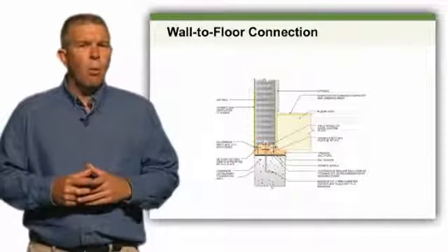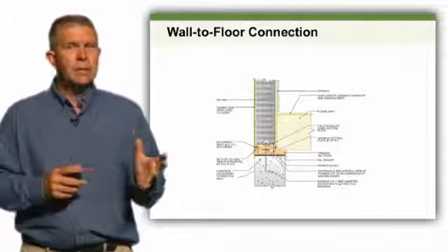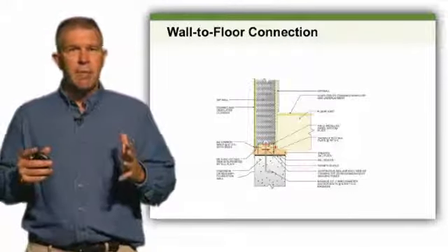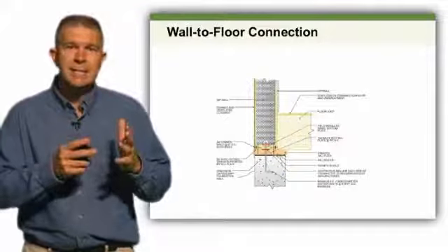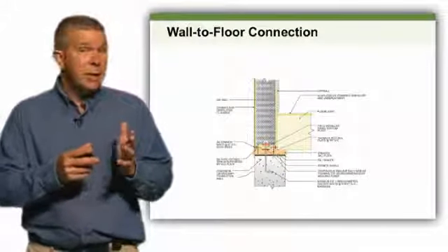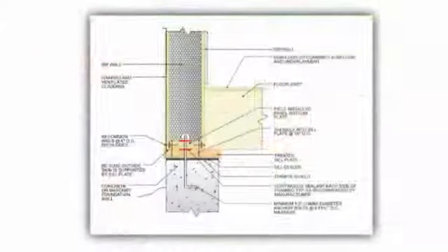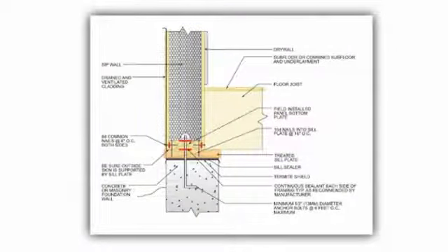If we're talking about wall SIPs, we have a couple of standard details that we're showing you here that incorporate the wall SIP as it attaches to the floor. Now, I say floor, it might be directly to the foundation. What we have here is a wall panel that goes down and caps the end of the floor system, and the foundation actually shares the support of both the wall as well as the floor system. In essence, what we've done is we're moving away from platform framing, where we build the entire floor system and then we put the wall on top of it.